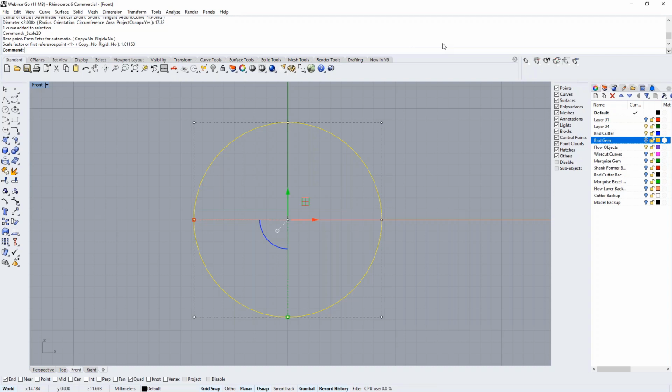If I do that, then it'll pretty much come out right on a 7, or actually it'll come out just under a size 7, which is what I like, because once the object is cast and I clean up the inside of the ring, I'll usually pound it with a rawhide mallet to make sure it's perfectly round and to slightly harden the metal of the ring.